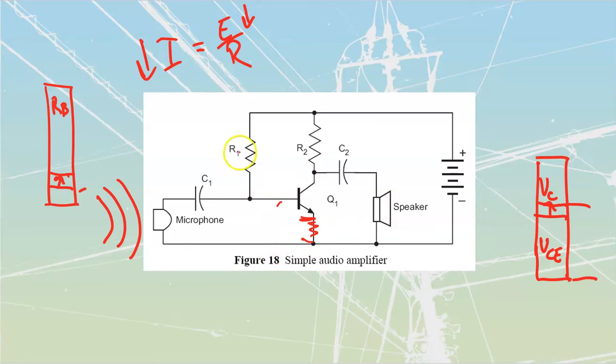Ideally, what I would do with this circuit is I would bias, and this would be if I was actually building a technical one over here, stick a resistor inside of there. I would bias this for a 24 volt system. This one over here, I would probably drop to 11 volts that I would have dropped across it. Then I'm going to drop 0.7 of a volt across this one, 0.7, which would mean that I would be dropping across here the remainder, which would then become 12.3. Somewhere roughly around there is where I would aim to be.